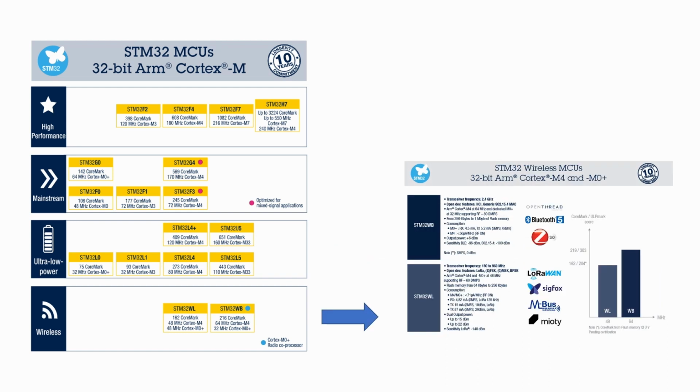And then lastly, we have the wireless family. These have built-in RF transceivers, making them capable of communicating over Bluetooth and LoRa and some of the other local wireless protocols that have really popped up for microcontrollers, as well as they also support GFSK, GMSK, and BPSK. So you can do more than just that. You could build your own SDR network if you so choose.